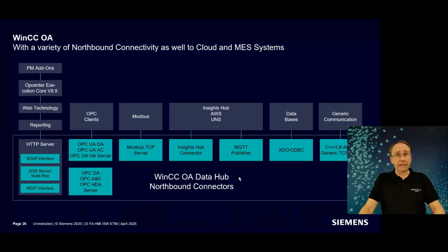For giving data via OPC, the old OPC, but also the new OPC UA, we have all types of servers in our system as well, not just the clients, which you have seen on the first page. There is the DA, data access, alarms and conditions, and historical access server, which we provide for both OPC UA and OPC technology. Modbus server is also available in the rare cases where you might want to use this, but literally speaking, OPC UA is the go-to standard.